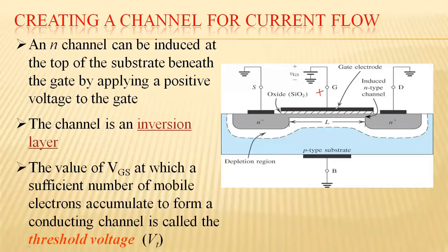Now, this is metal, and this generally acts as a parallel plate capacitor. So this gate, and in between you have silicon dioxide. This silicon dioxide acts as a dielectric, and this gate metal plate, and the region below this silicon dioxide between source and drain, this region acts as one more parallel plate. So this acts as a channel.